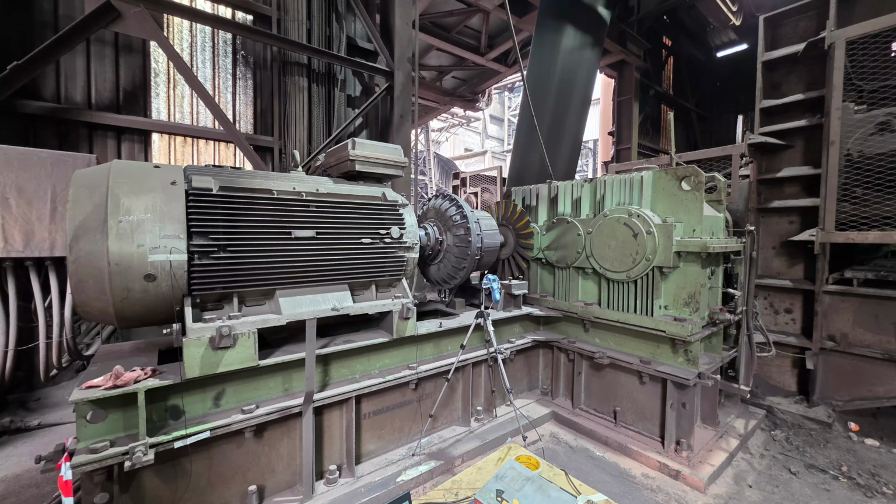Any rotating equipment will have some residual unbalance, even though the components are balanced as they are manufactured, component by component. But once they are put into an assembly, here we are talking of a large motor, its output coupling, then a gear coupling, then this fluid coupling, then the output gear. There are so many rotating parts connected. It is obvious that there will be some residual unbalance. And this residual unbalance, because of the sheer size of the coupling itself, can generate a good amount of centrifugal force and the related vibration.